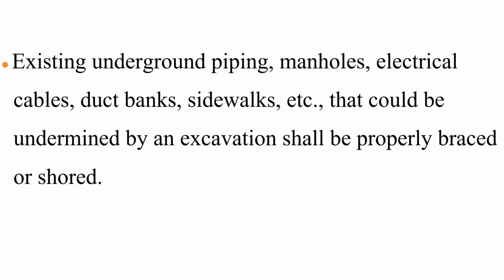Existing underground piping, manholes, electrical cables, duct banks, sidewalks, etc., that could be undermined by an excavation shall be properly braced or shored.